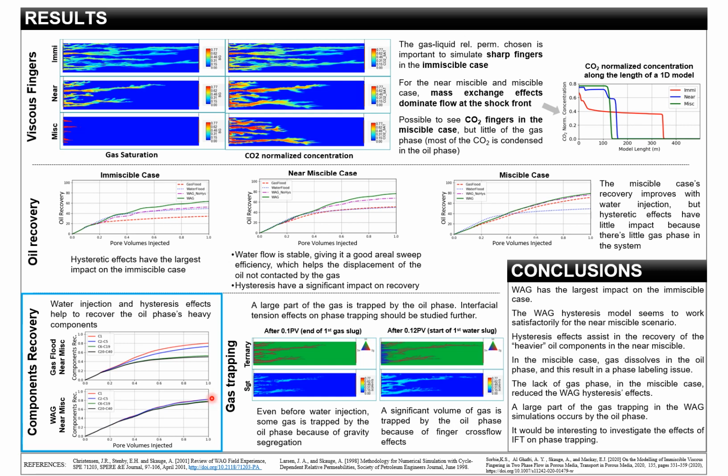One is that the water displaces all the oil components equally. So just by injecting water, we reduce this spread a bit. But also, WAG hysteresis effects mean that when we trap gas in our model, we are reducing the oil residual saturation. And that means that the heavy oil left behind, which has a small saturation and is immiscible with the gas, and so is otherwise not very mobile, now, when we reduce the residual saturation for the oil, becomes mobile, and so it can be mobilized by both water and gas.